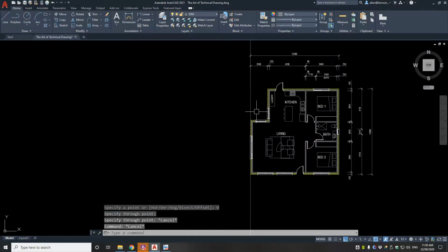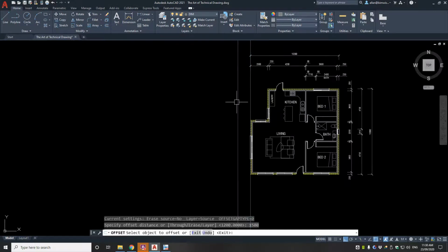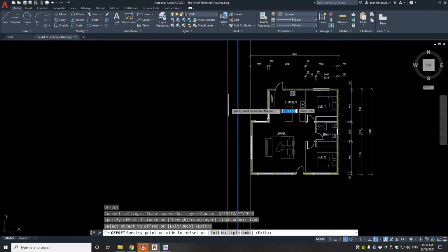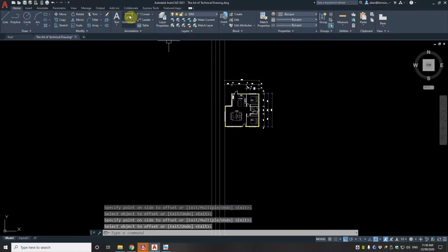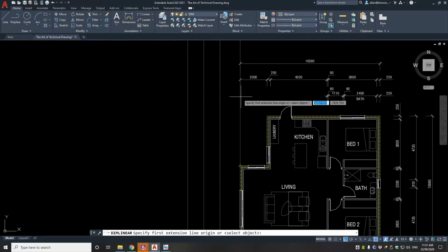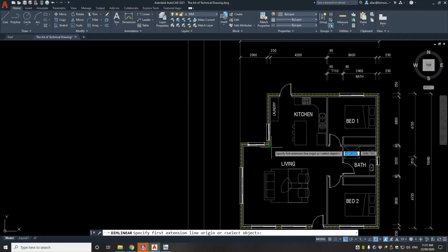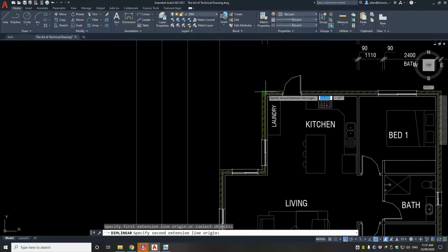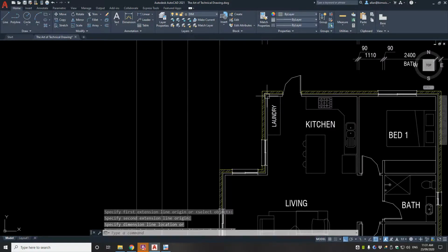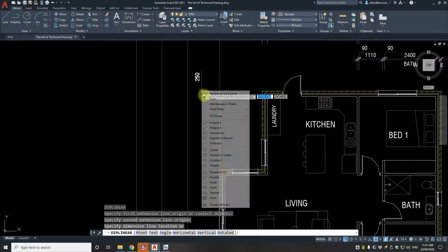Put in our construction lines here again, 1500, offset 1200, which was the same as the other side. We're going to have 3 strings there as well. So with dimensioning, you normally start from the inside and work your way out. So in this string, I'm going to dimension internal walls, windows, then overall. So it's small to large, inside out. And I do know something on that living room block that I'll show you in a minute too when we finish this dimension string.